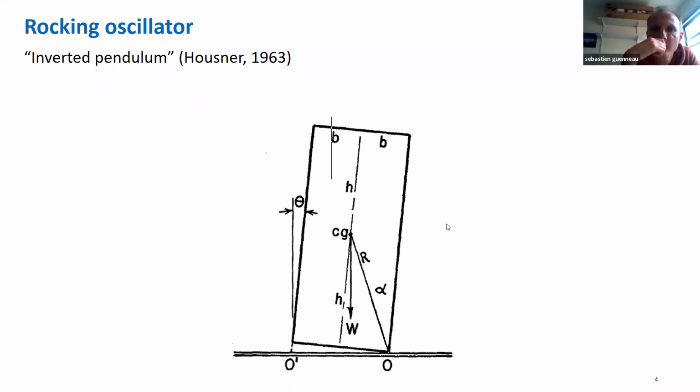I mean, frankly speaking, I've never thought of it. What I studied some 10 years ago is what happens if you have a column and another column next to it and another one, and on top, a beam. Which would be a rocking frame, which would be the Parthenon. At least 2D. A very interesting observation is that it emerges directly from the differential equation that the frame is equivalent to a column that has the same slenderness alpha, yet larger size.